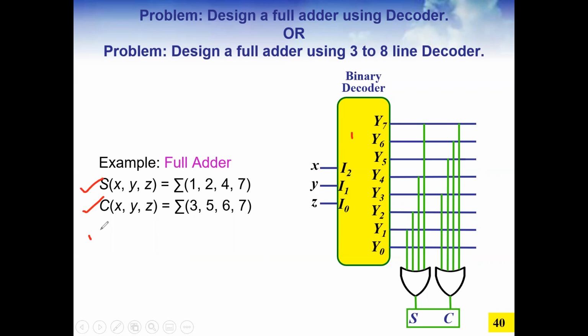If you want to add more inputs, no problem, you can use 1 decoder, but you need to increase the OR gates. Here you can connect more. So the number of expressions is equivalent to the number of OR gates. 1 decoder is enough, because the decoder generates the minterms. So with 3 inputs, 8 minterms are generated; you check according to the function which minterms are present, just connect accordingly, and this is the way.